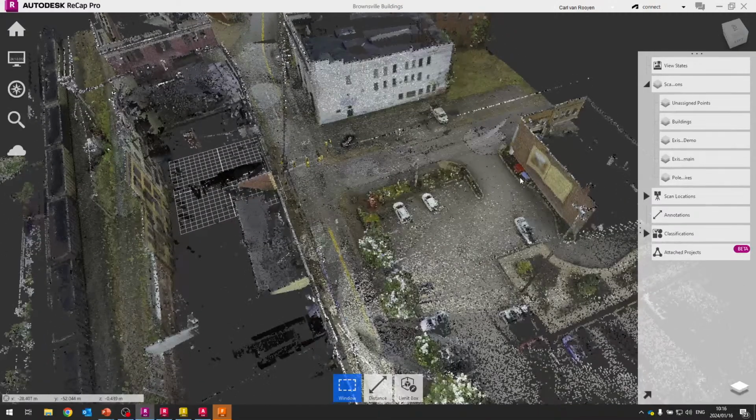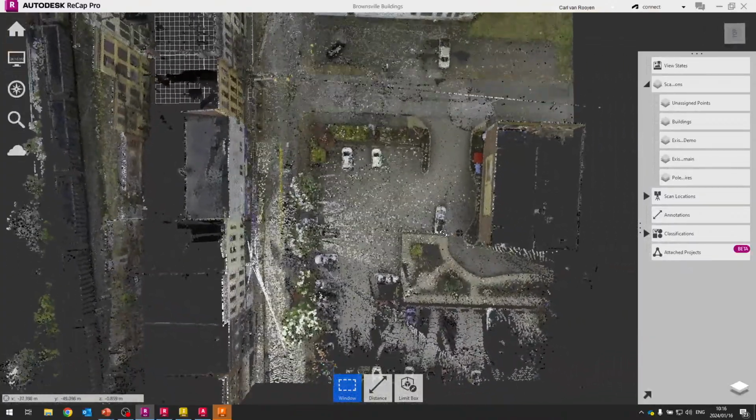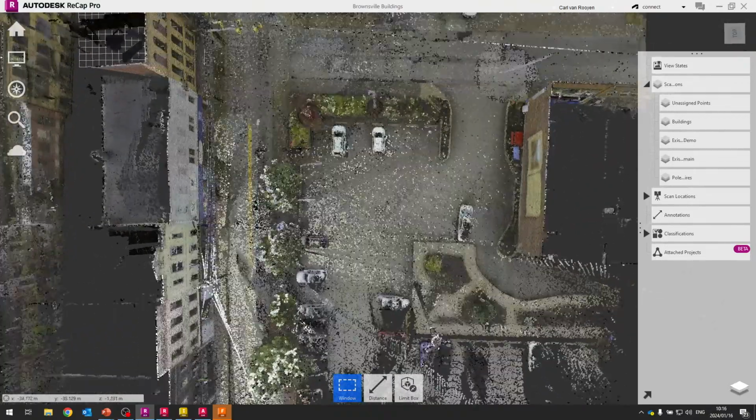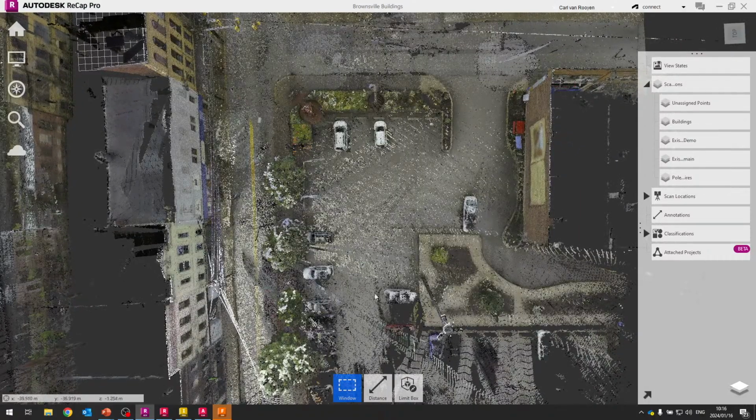So let's first create a region. I want to create a parking lot region here for this parking lot. Maybe we need to design a cover for the parking lot. They want to put shade cloth up or a solid roof structure up, maybe for a solar installation or something of the like. So at the bottom we can grab, let's say, just the fence tool to identify the area that's going to be covered. So let's say we're going to do something like this here, around to the front of the building.